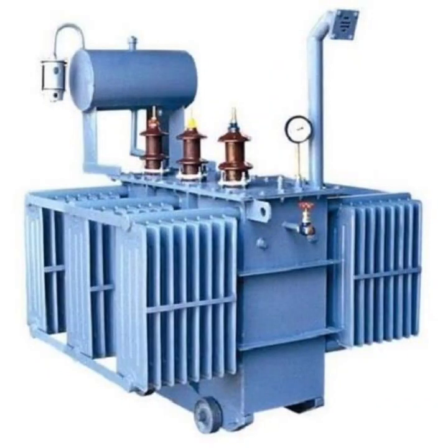Now third type, based on coolant material. Under the coolant material, the first type is oil-filled self-cooling transformer. Oil-filled self-cooling type is used for small and medium-sized distribution transformers. The assembled windings and core of such transformers are mounted in a welded oil-tight steel tank provided with a steel cover. The oil helps in transferring the heat from the core and the winding to the cast iron where it is radiated out to the surroundings.